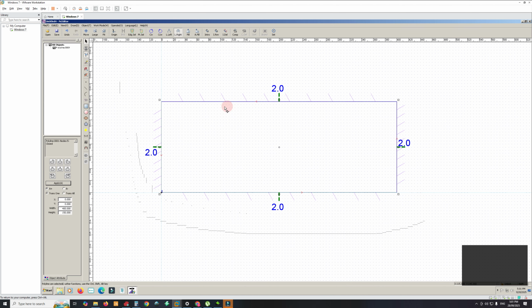At the moment you can see it's going counterclockwise by these little red arrows. This is the movement of the machine head whilst cutting. So we want to change that to clockwise. That has now moved all these diagonal lines in, showing that we want to keep the internal part of this bench, and all our angles, these green lines, are going to be cut 2 degrees in towards the centre of the bench. We're going to change that later.